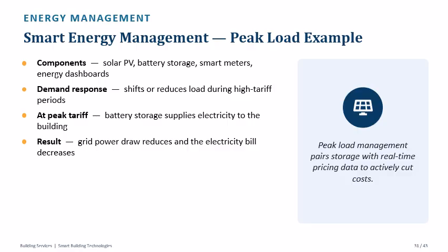The demand response shifts or reduces the load during high tariff periods and at peak tariff. So the battery storage supplies the electricity to the buildings, and as a result, the grid power draw reduces, and the electricity bill will be decreased.